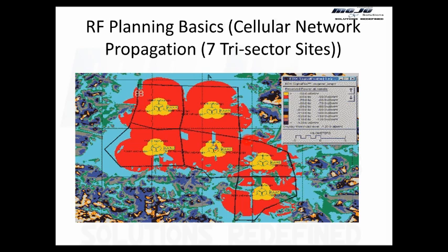They also predict not only signal strength, but also the throughput you should expect at those locations, based on different simulations. This is an advanced level of simulation; the concept behind them is the same, but the logic or the mathematics used behind them is different. We will learn those simulations. For example, to simulate a UMTS or LTE network, it also depends on the distribution of the users.